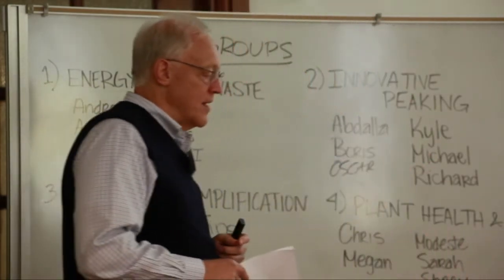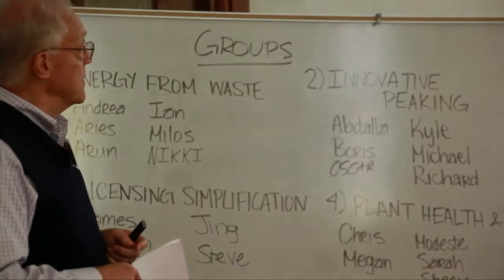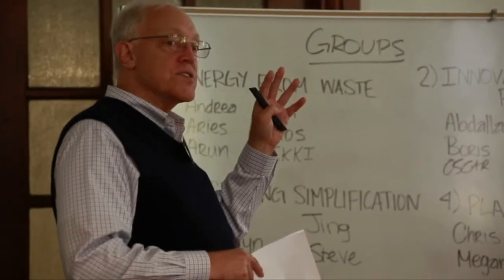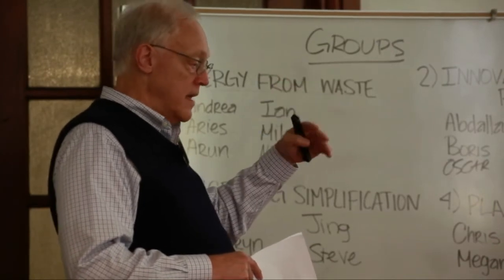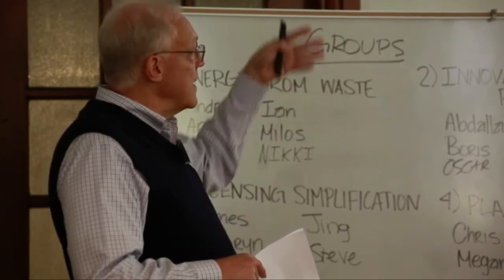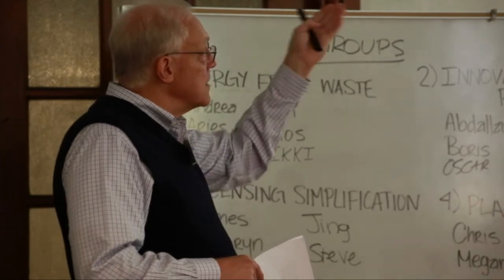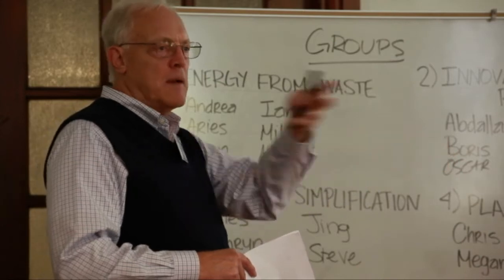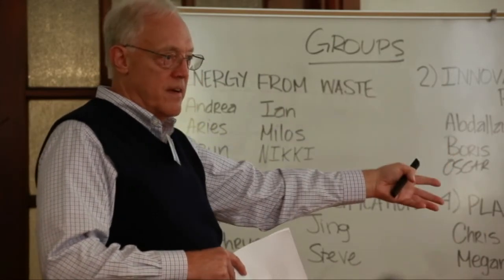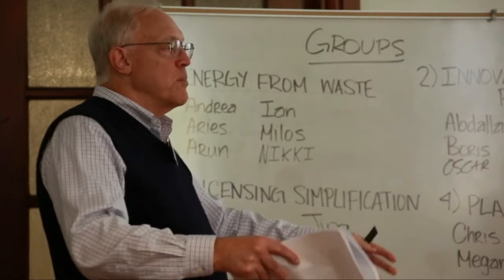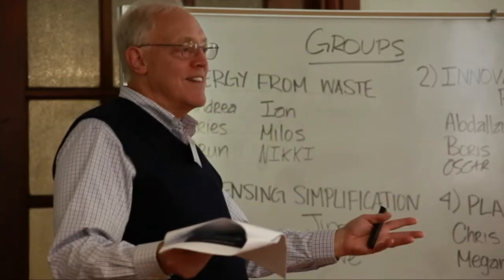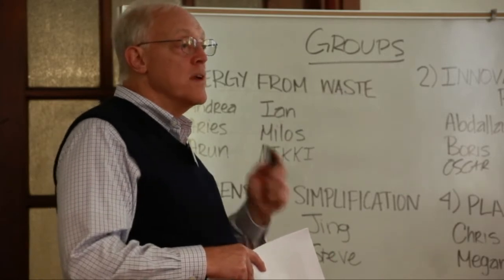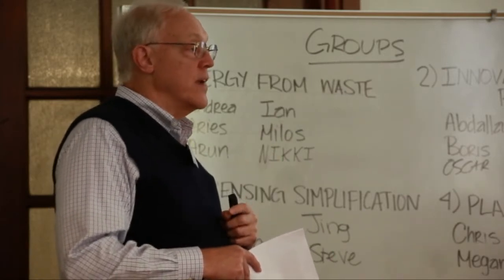Quick run through just to give you a preview of some of the things we're going to talk about. Now these are management in the sense of operations management and plant management examples where, I'll take Davis-Besse in 1985. They should have gone to feed and bleed. I presume that concept at least generally is understood here. Basically we lost all decay heat removal in the plant. We should have been in feed and bleed. Management made a decision not to go there.